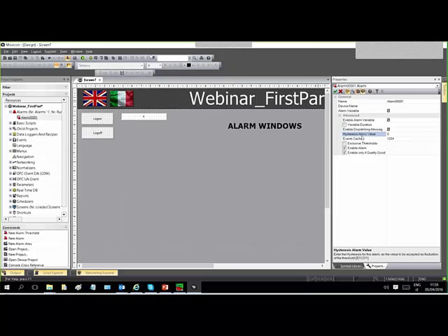Enter the hysteresis for this alarm, as the value to be accepted as a fluctuation of the threshold. Enter the maximum cache value before starting the recycle. When this value has been reached, the oldest event will be discarded. And so on. Enable, disable. This is quite important: enable only if the quality is good. This is the default setting. The alarm will be enabled only if the quality of the associated variable is good. This means that if you lose the communication with the PLC, the alarm will not appear in the alarm window if you keep this flag.